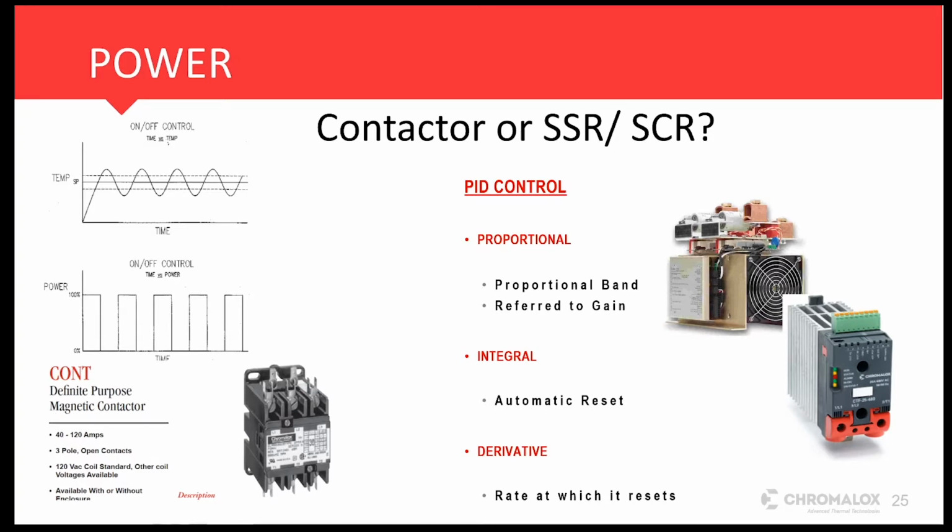But if you're working with an OEM and they're needing 50 or 100 of these a year, probably we're not the best place to get that from, as they're pretty expensive compared to what they can probably get at something like Home Depot even. So if they are not using a contactor, they're almost certainly using an SCR. And that's when you're going to get way more control. PID control is a lot more functional on these types of controllers. The cycle time is way faster. There are no hard mechanical components that can get worn out. So yeah, 90% of the time you're going to run into either a contactor or an SCR. So that's the first question.